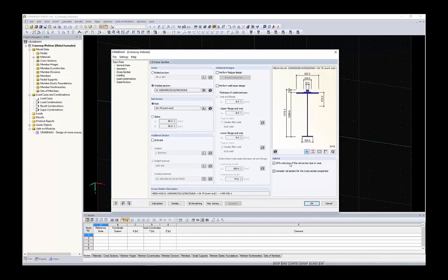On the right side, you can also see that you can take the weight of the rail section into account, defined by the standard. As you can see, the section properties are modified automatically. You don't have to do anything. You get some info in the section of the rail. And in this case, I have an elastic support under the rail, so I don't want to take the rail section into account for the section properties. I will just switch this checkbox off,